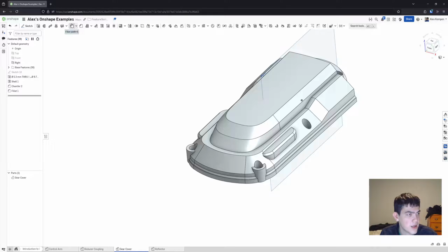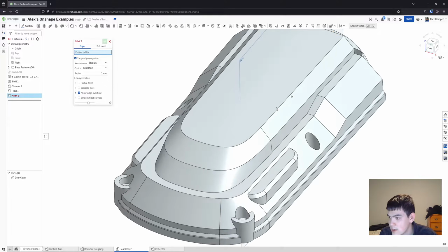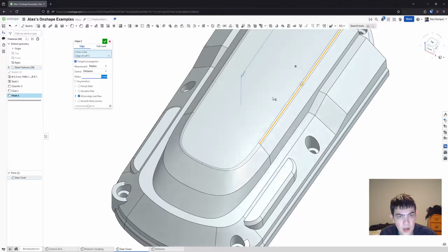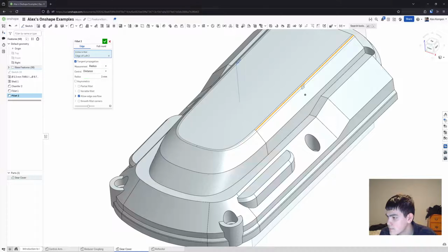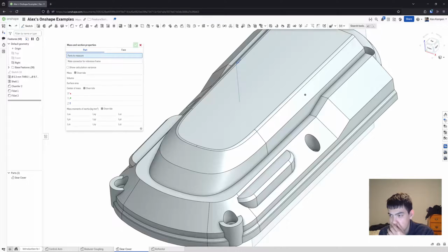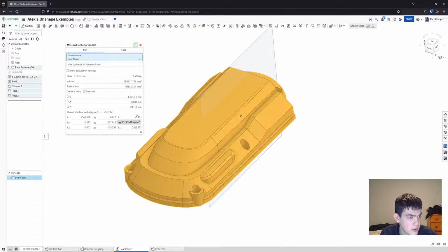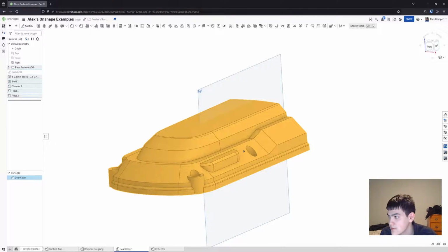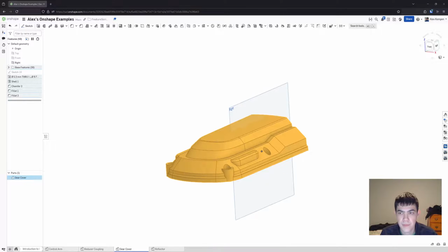Okay, cool, and now we're gonna add another fillet to the top. And this guy is gonna be 3 millimeters. Right. Once again, tangent propagation makes it easy for us. And that looks pretty good. So we'll go ahead and confirm that. And so now if we check our mass of our part, we can see our mass is 0.445 kilograms. So if I go to do the self-check, we can see that's correct. So we did it. Cool.